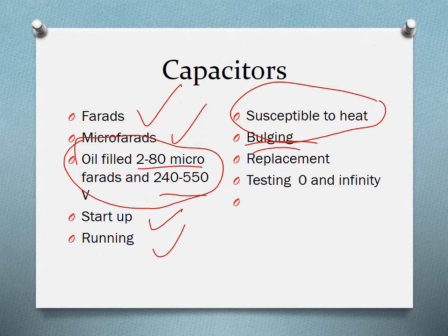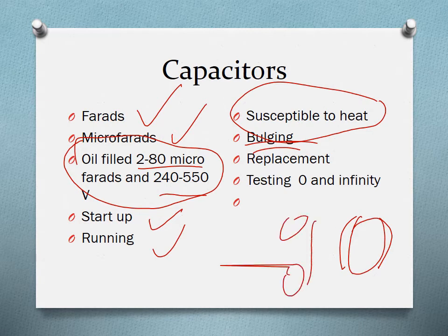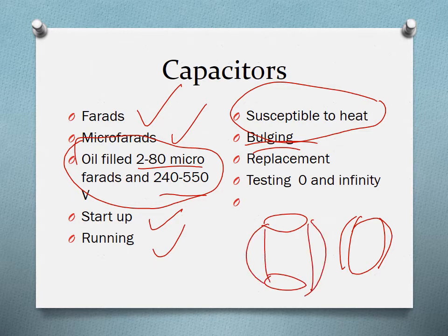Bulging: if this is a cylinder here, and it gets bulgy, this is bad. If you have a cylinder here and it starts to bulge, that means the capacitor is going bad.